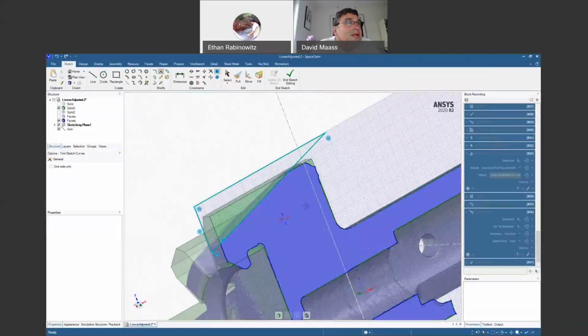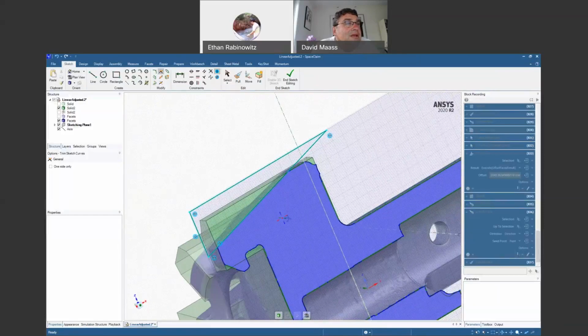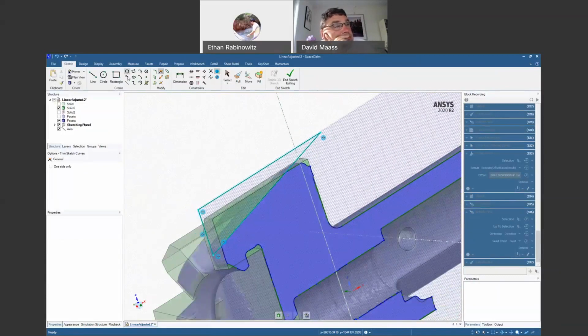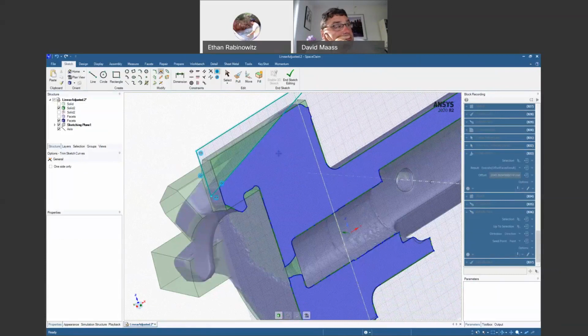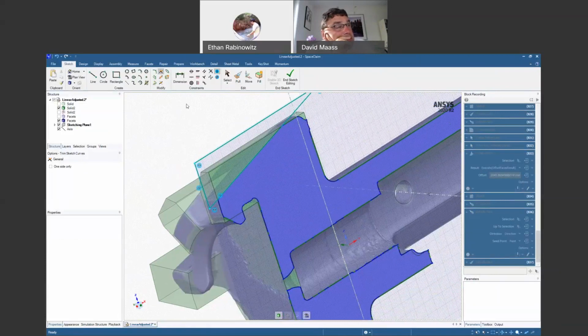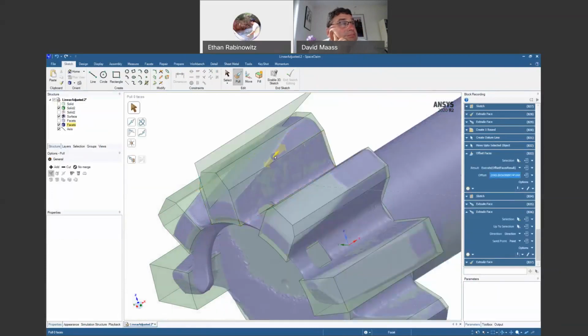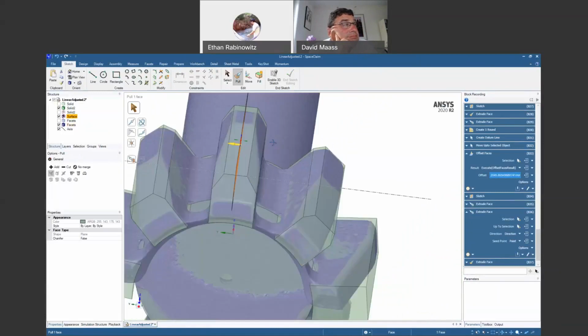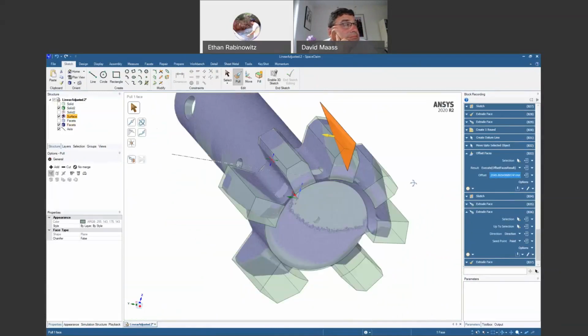Again, not going to dimension it. We always do that, or we know how to do that. So we've got that. I think that is all we need for now. So we'll go to pull. Pull brings us out of a sketch just like the check mark does. And I'm going to take this piece here